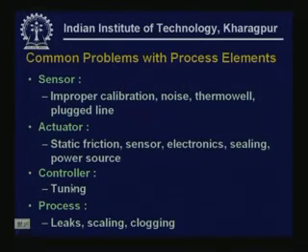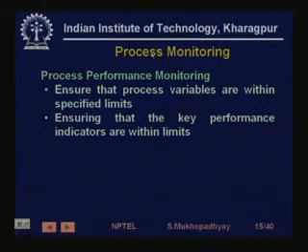Similarly, the controller may be badly tuned, right? And of course, the process can develop leaks. It can develop scales on heat transfer equipment. Things can get clogged. So, all these kinds of problems can occur, and these problems generally make the performance of the control loop inferior. So, one needs to check all the time whether the control system is actually performing adequately. That is the basic job of process monitoring.